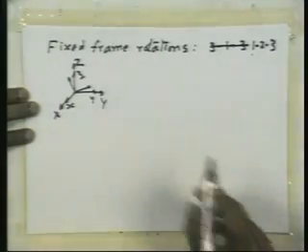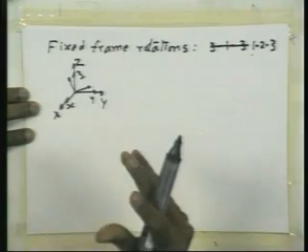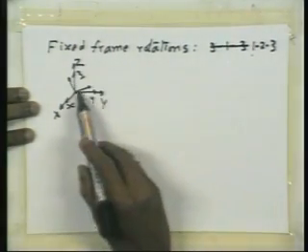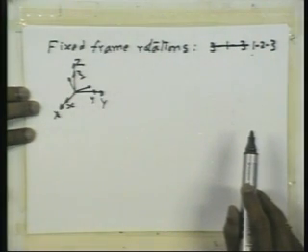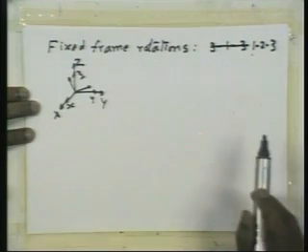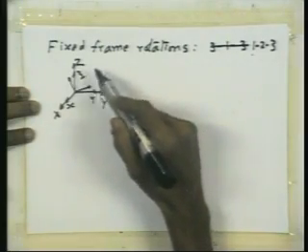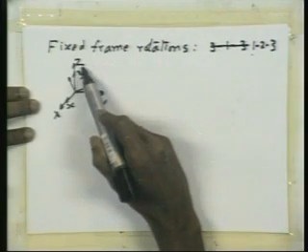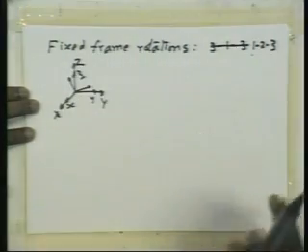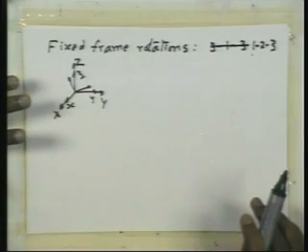Next, you rotate about the y axis of this body, which is already rotated about this particular axis. Fine, that's what is done. So this small x, y, z, the new positions will go somewhere else, and after that you rotate about the global z axis, and you get the final position.